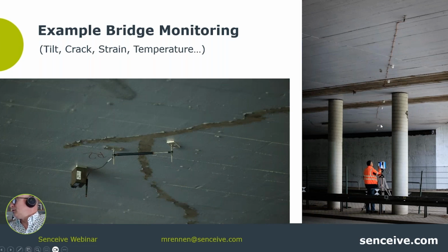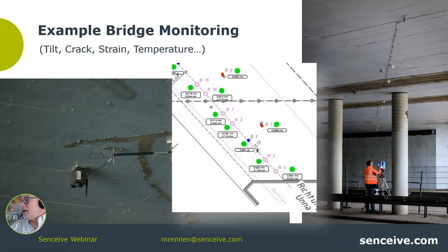And here you see basically the whole installation. Here on this bridge field, 1, 2 tilt sensors. In the center here, a strain gauge, and then tilt sensors. Again, same on this bridge field here, and that same parallel on that side. So again, here, overview, tilt sensors here, center strain gauge, and then tilt sensors there again. On this line, basically below the outer lane of the bridge, where the majority